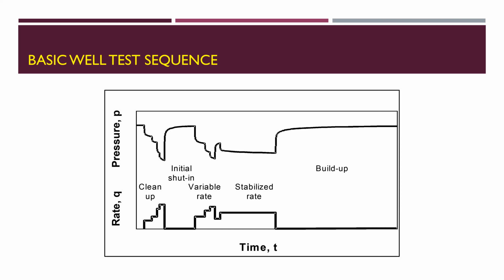If I feel that I didn't achieve my goal and radial flow still hasn't been reached, because most of the time it is masked by wellbore storage and the transition period, this is why I'm telling you, it depends on what facilities you have. If I can monitor and analyze on time, I can decide on time either to shorten the well test period or to extend it further.